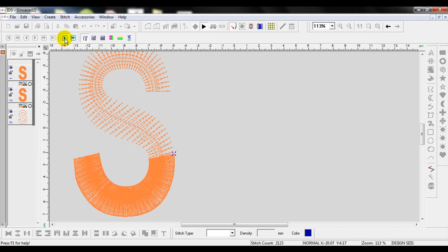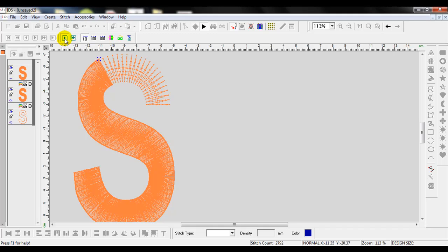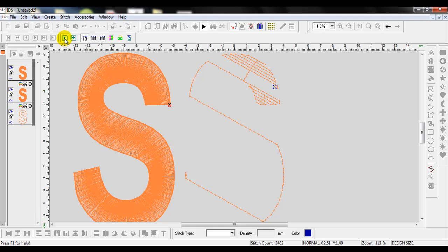Then you see it come on top and do what we call the cover stitch, and in this case it's doing a satin stitch. This is that final stitch that we see, and it goes over and covers on top of the underlay. Now in addition to the underlay helping that material stabilize, we do have the stabilizer or the backing in addition.